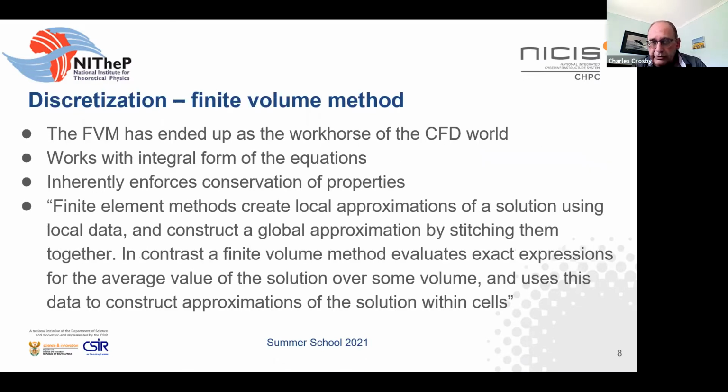Okay, I just want to take a look. I see there's a question that came up. At what point when using first order can one say it's satisfactorily accurate to switch to second order schemes? Yeah, Andrew's got it right there. Certainly I would agree with that: when the second order solution will run stable. In other words, ideally, you don't really want to start first order. Ideally, you want to start second order. So you start second order.